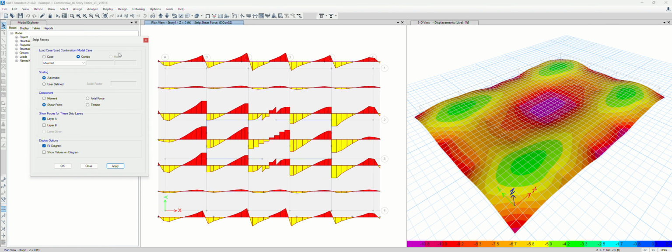Alright, so what you see are the shear forces based upon 1.2 dead load plus 1.6 live load. Now it looks like something you're familiar with, because this is a continuous spring instead of just one or two supports at each end. So this is something like an equivalent continuous beam supported by continuous springs. That's why you see the spring constant.